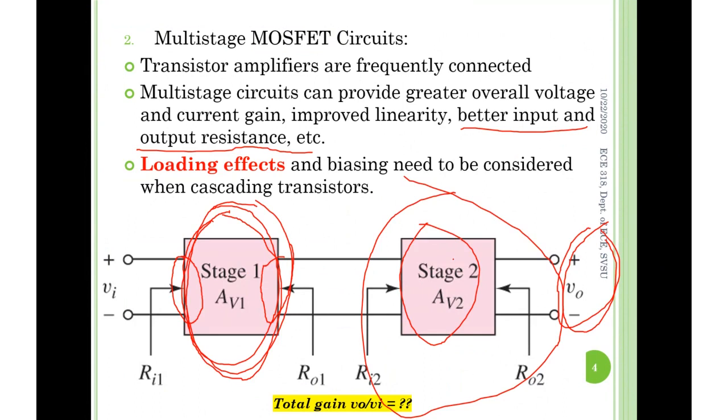Because you will see that different amplifier circuits have different features. Only the common source amplifier has big enough amplification gain. The common drain and the common gate don't have big enough gain and can't contribute much, but they have very good input impedance or output impedance. That's why they are also useful, because they can be used as the front end or the back end stage.